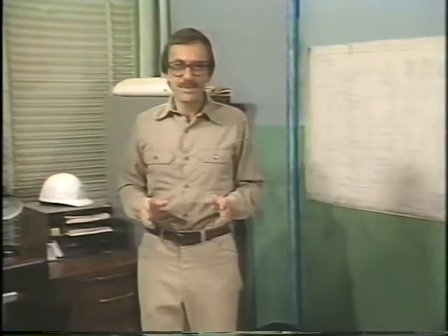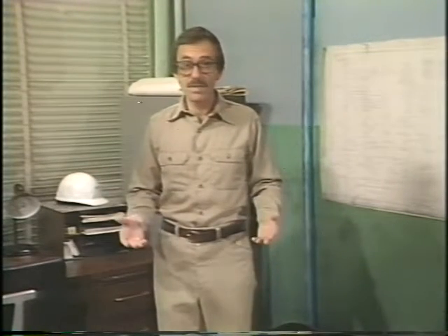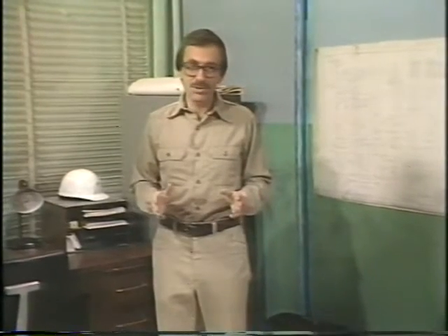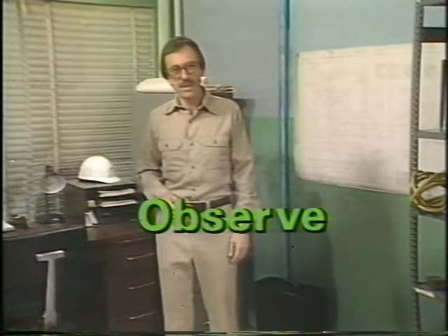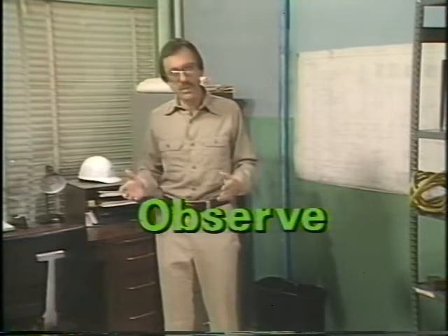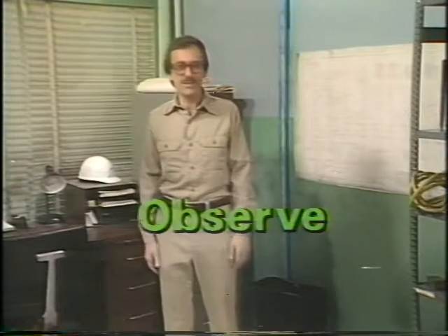And we've been able to see then that in troubleshooting instrument systems, you'll first be notified of the problem by having your foreman tell you about it, or by receiving some kind of written notification like a work order. Then to begin troubleshooting, you start by preparing. You familiarize yourself with the normal operating conditions of the system. Once you've prepared, you'll be ready to move on to the next part of the troubleshooting procedure, to observe the system. In other words, you'll be prepared to go out and actually take a look at the system's indications.